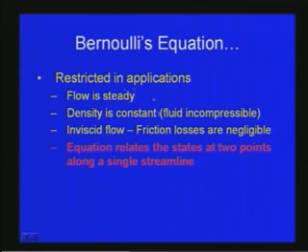In many practical problems these assumptions are difficult to apply, but in certain cases we can approximate the flow, even though the viscosity is to be considered. Whenever water is concerned, since its viscosity is small, or air flow is concerned, where viscosity is small, we can use this Bernoulli's equation. So the assumptions are: flow is steady, density is constant, and inviscid flow.